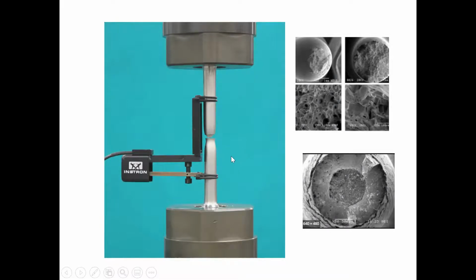So we're stretching it. We're increasing what's called the elongation. And when we do that, the crack is starting to form here. And because this material has some ductility in it, you can see it's necking, it has become thinner in the middle than the rest of it. So if you look here, you'll see a slow decrease in the diameter, and that diameter decreases more rapidly as we come to the point where it's broken. And you can see it more obviously here. You get this sort of bottleneck effect. This is called a bottleneck because it looks like the neck of a bottle.